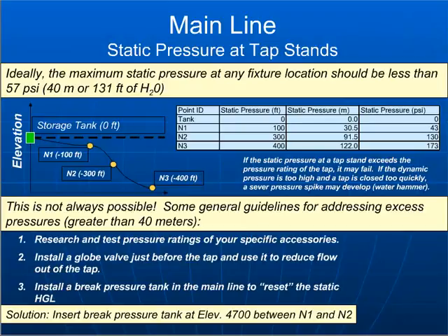A lot of this is actually more of a concern in applications here in the U.S. if you have any type of appliance or valve that's controlled by a solenoid, where the valve is turned on and off very quickly. That can cause even more problems. The good news is if it's just a tap where you're required to turn it on and off manually, the rate at which the tap is closed can help to alleviate some of these concerns about water pressure.